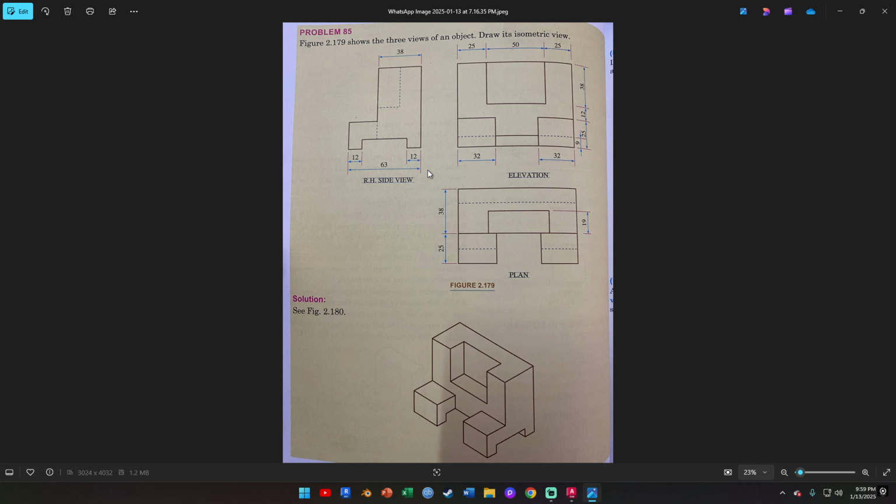You can see that the total length is 63. And we know that this total length here on the left receding axis is going to be equal to this total here, when you add up these three numbers. So you have 25, 50, and 25, which gives you 100. So we have two measurements here already. We have the 63 mm and we have the 100 mm.